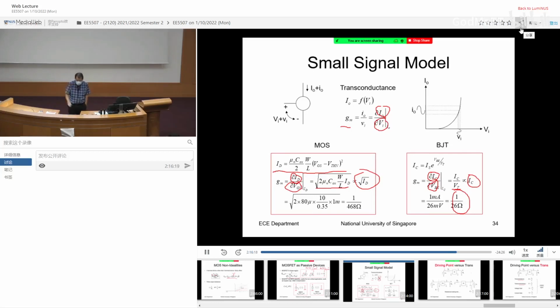So yes, you can have higher GM, but you forgot to take into consideration the frequency of the operation. So it might get better GM, but that only happens at lower frequency. Higher frequency doesn't work. So that is the reason for ECG, they do that. What is ECG? How fast does your heart beat? 60 per minute or 1 per second. So what is the frequency range? 100 hertz. Good enough already. Right? So subthreshold is okay. Get the point?